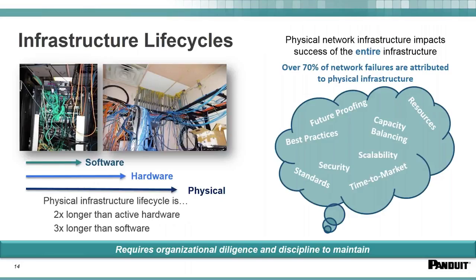It's very important that we understand that the infrastructure that we're putting in is going to have to outlast a lot of the other manufacturing aspects. So the hardware that we deploy, the network switches, controllers, devices, typically we will have to use the same infrastructure and replace that hardware 2 times. And the software that's used on the network, such as the data historians, OEE, and other types of HMI software, etc., all that's going to be replaced 3 times over the course of the network.